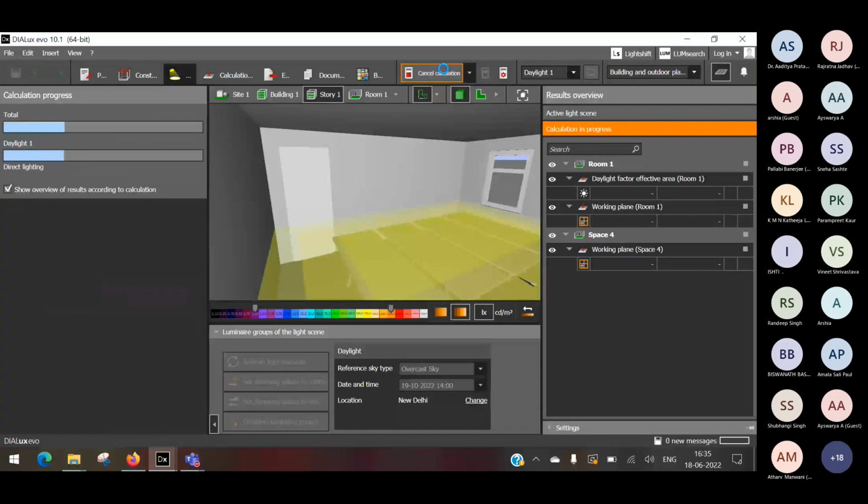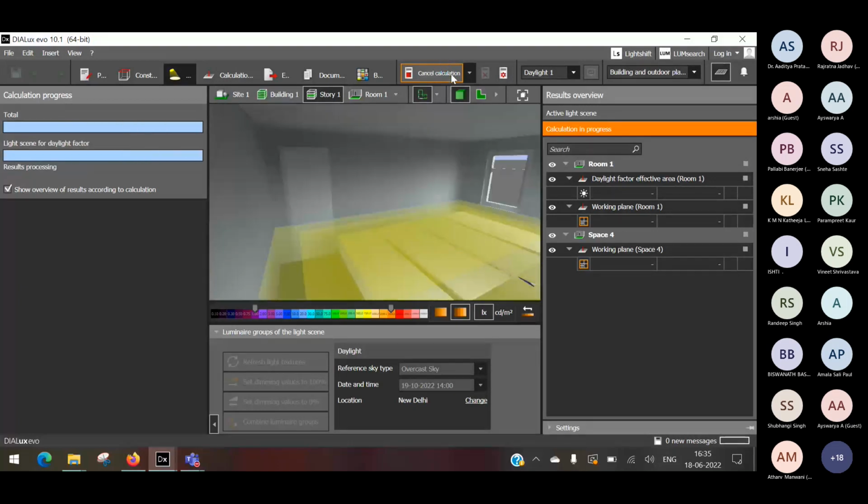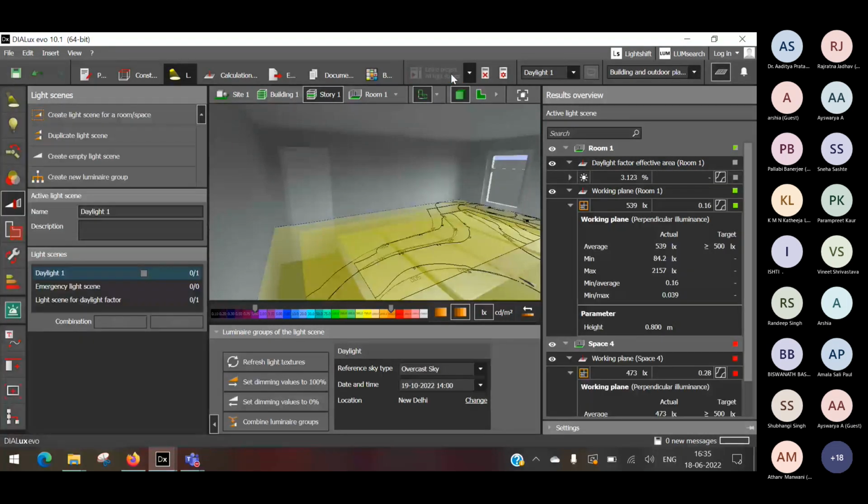See, daylight factor is a concept which came up probably in the 1960s, wherein they tried to discuss the worst case scenario, and in that worst case scenario, how much light you get during the day. The worst case scenario in such a situation would be on an overcast day when light is minimal, or the sun is at an angle of 15 degrees above the horizon.